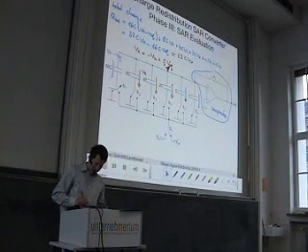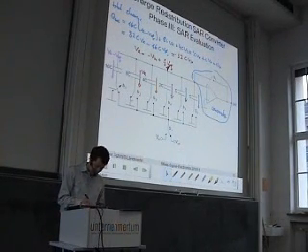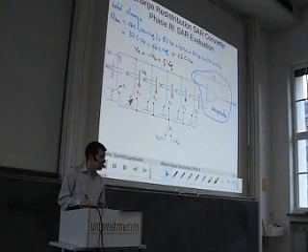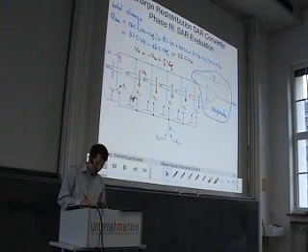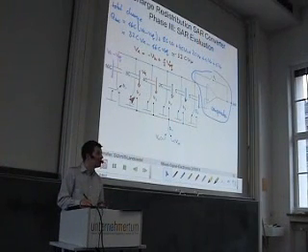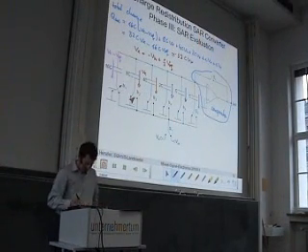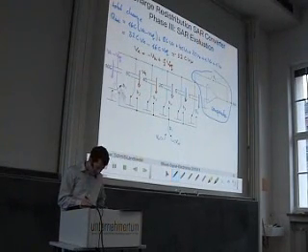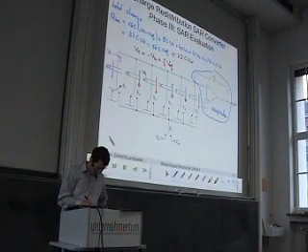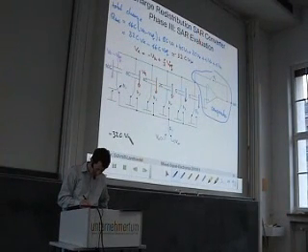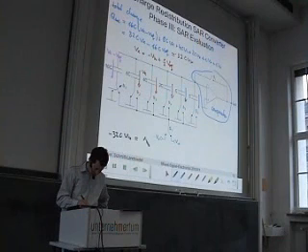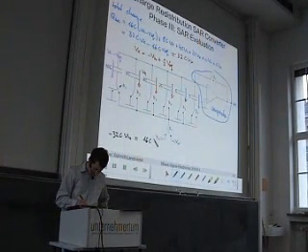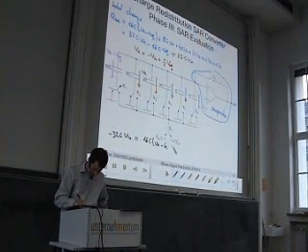And then we can do this for the next switch. We can now continue with this one and search for the next bit. And by doing this, we say, okay, depending on the decision that we had here, we had a total charge which is minus 32C Vin. And this has to be equal to 16C Vx minus B1 Vref.